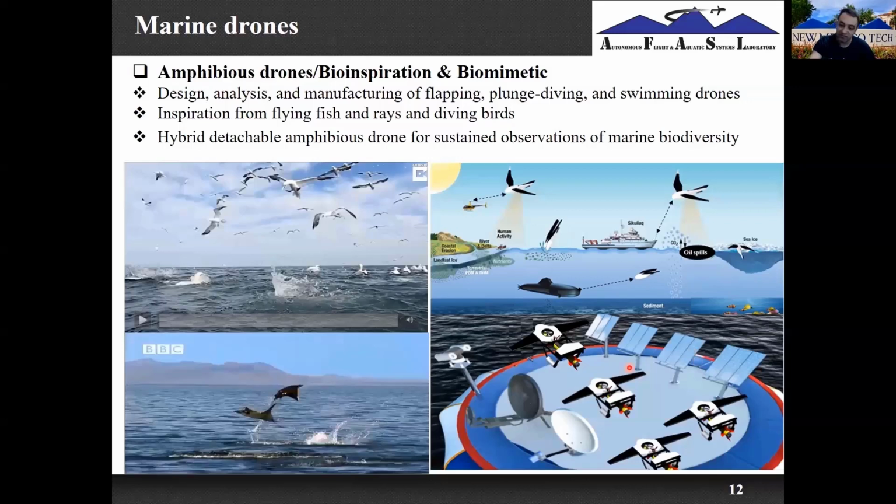These are drones which can fly over the ocean and harvest energy from the shear wind over the water, like albatrosses changing the banking angle for dynamic soaring. Or, for example, they can land on the water. We always have water waves over the water, so once you've landed on the waves, as we can see here, they can harvest energy from this type of motion, and we can also integrate solar panels at the top of the wings.